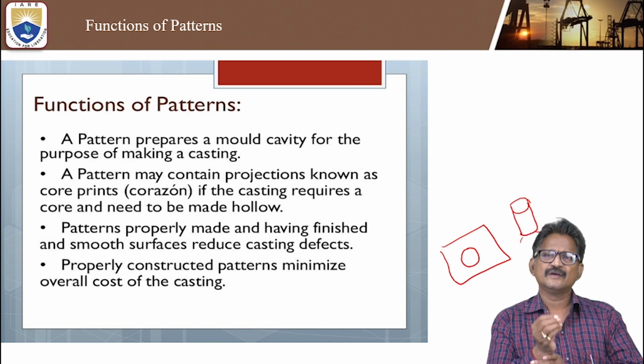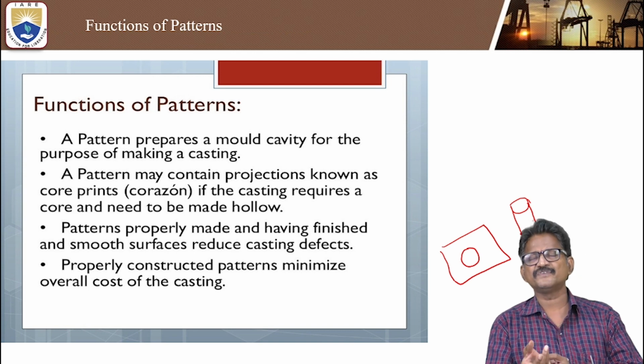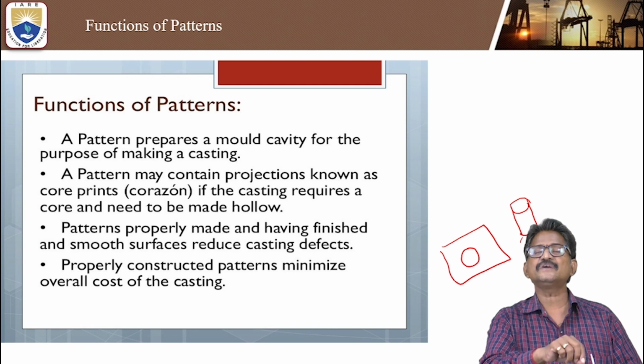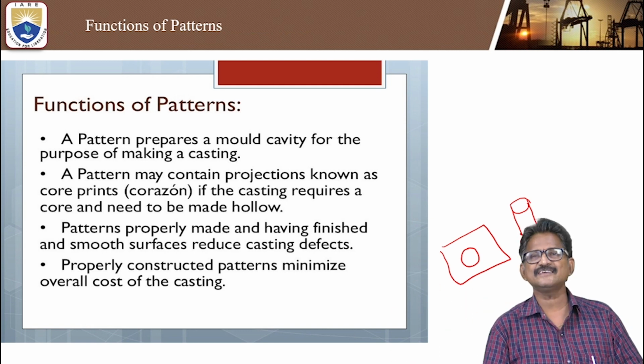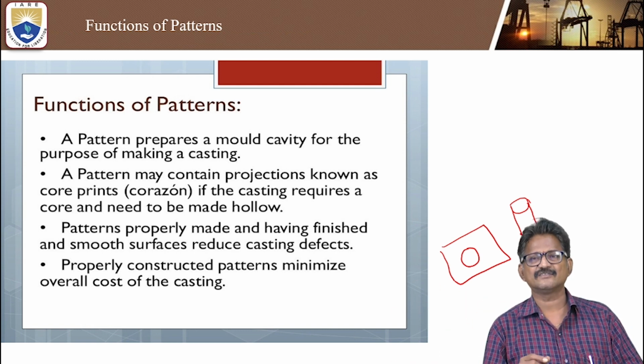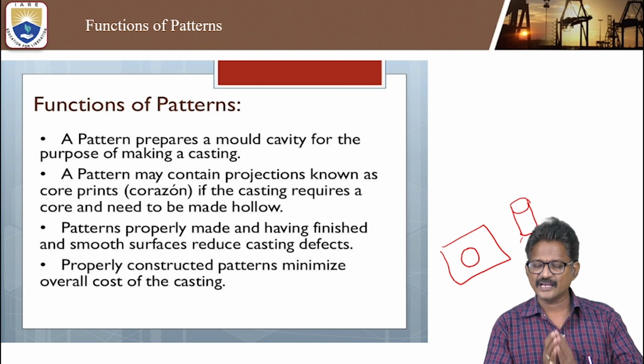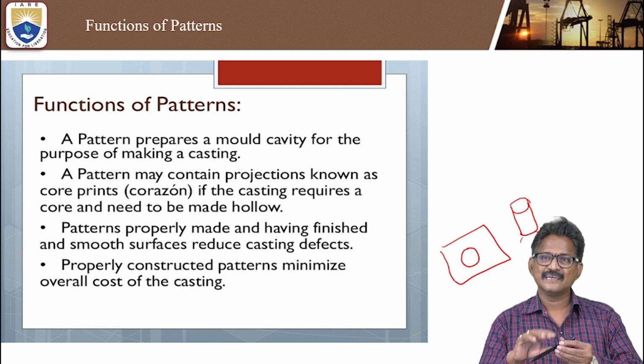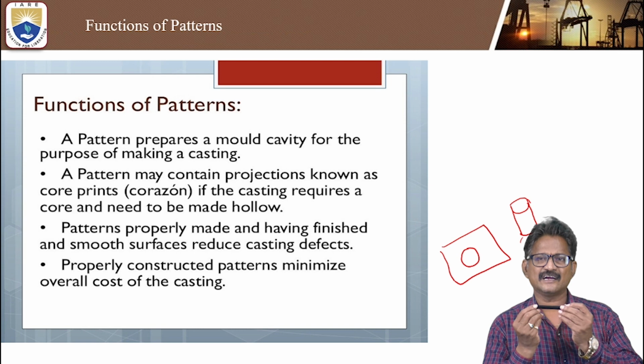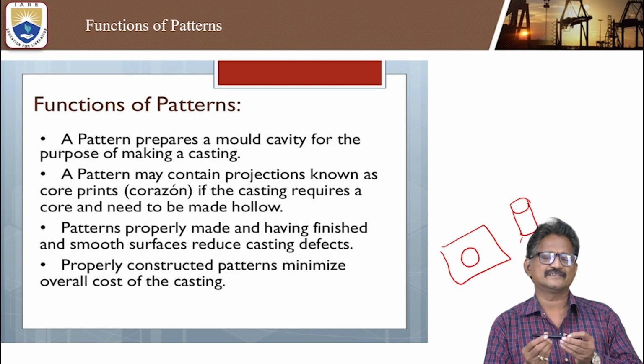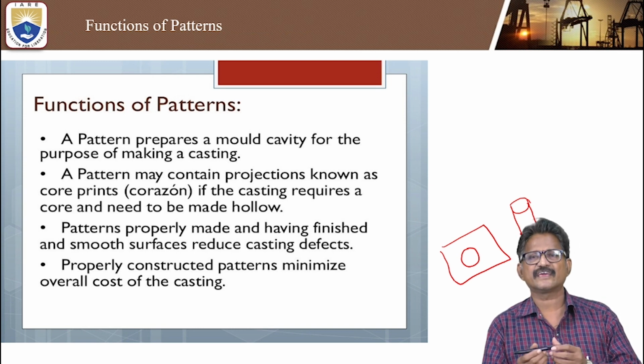Suppose if any unfinishing or some extra particles are there, that leads to defects in the final casting. So that is why you can assume that a pattern should have a clean and good surface. Then only you will be able to have a sound casting.